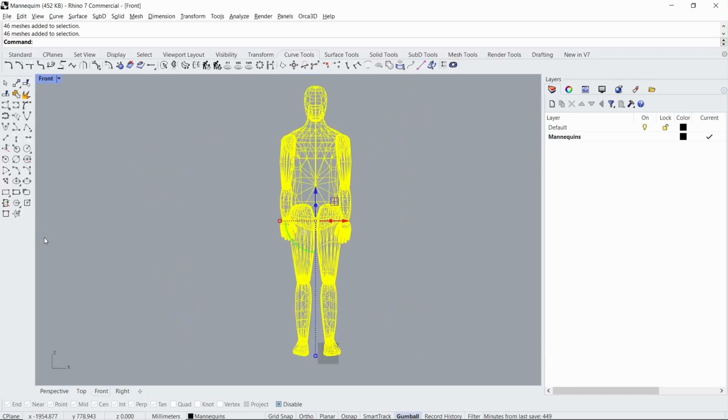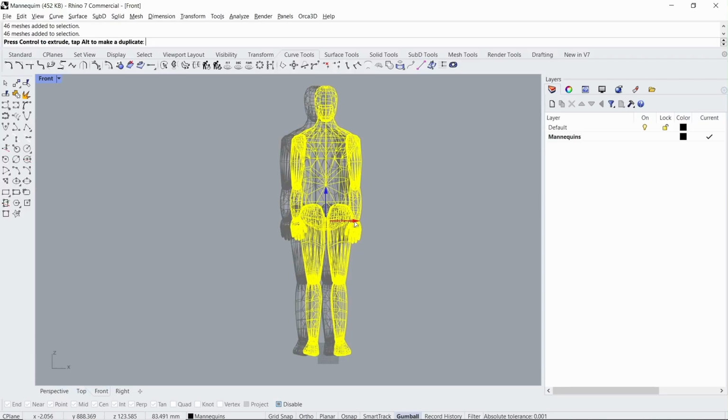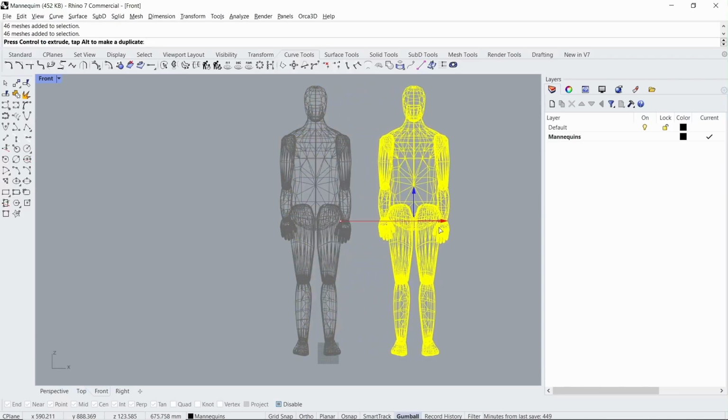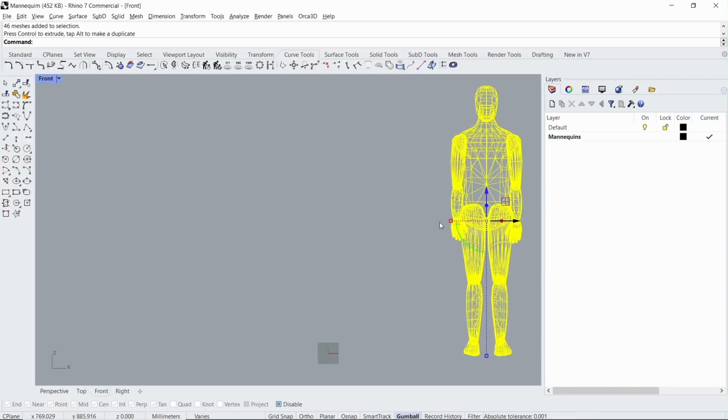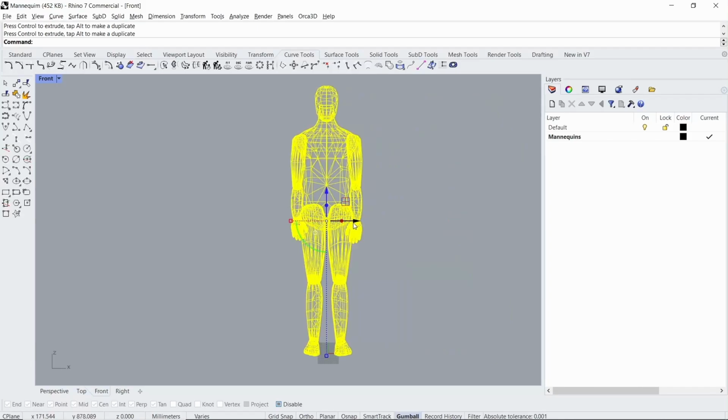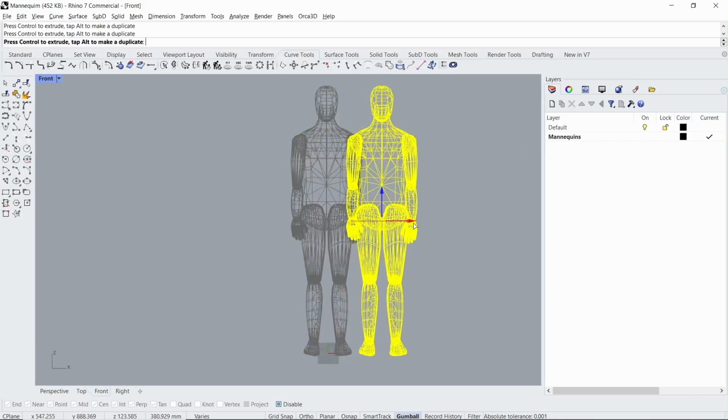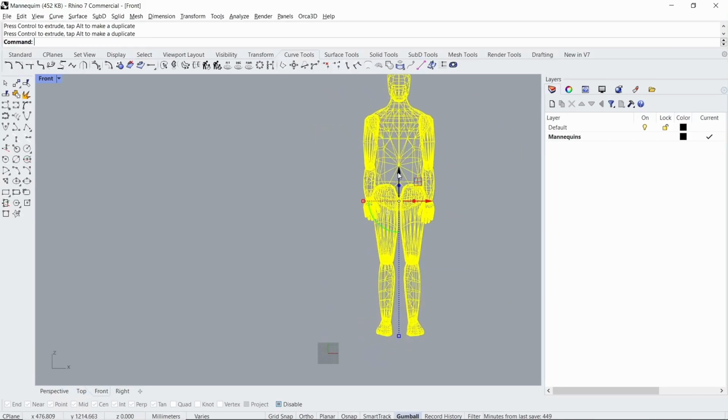So the first modification that we can do is to move an object, and we can do that by using these arrows. We can left-click on the arrow, pressing it with the left mouse button and dragging it to the side. Then you're going to move it. You can also give one click on the arrow and type the amount that you want to move the object. Have in mind that the amount that you're going to type will be the same unit as you have your system predefined. Here it is set in millimeters, so 500 millimeters. We can make movement longitudinally, vertically, and on both directions at the same time by using this little square.